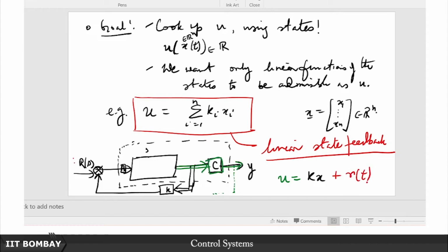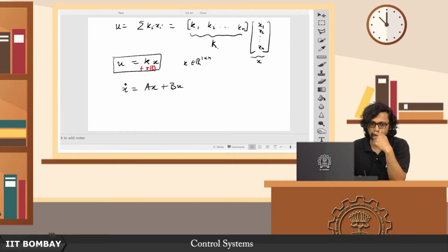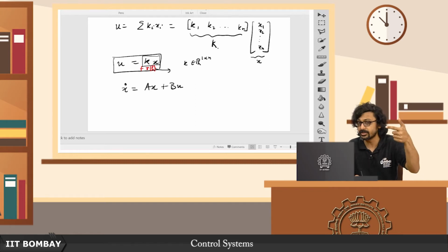So this Laplace inverse of this big R is the small r, right. So this reference input has to be still there. By the same token here, we will also add this term r of t here. Now if we plug this back in here, remember why this r of t is coming, because this part is just coming as something that is internal to the system, but this is the exogenous signal, the external signal, the excitation signal, that has to be always there, that is the externally applied reference signal.